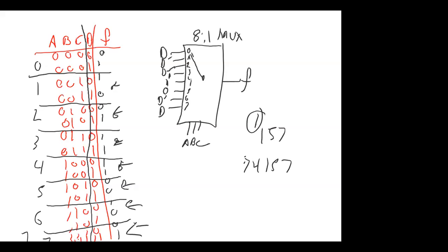So that's the, I don't know, bird's eye lowdown on the multiplexer caper. So that's pretty cool, right? We've got 2-to-1 multiplexers, 4-to-1 multiplexers, 8-to-1 multiplexers. If an 8-to-1 multiplexer can implement a 4-variable truth table, how many variables do you think a 16-to-1 multiplexer could implement?